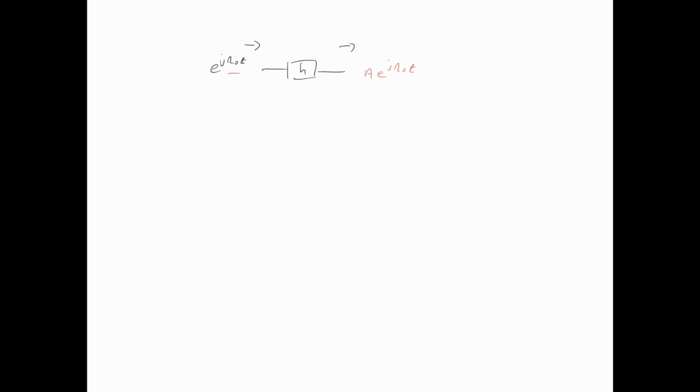You can show this is true by taking the convolution equation and substituting in a complex exponential sinusoid and seeing that you get out another complex exponential sinusoid, just possibly with a phase and magnitude shift, determined of course by the channel impulse response. This coefficient a here depends on the frequency omega naught, and so we're going to call it h of omega naught in this example here. We will see presently that my h here really is the Fourier transform of the channel impulse response.